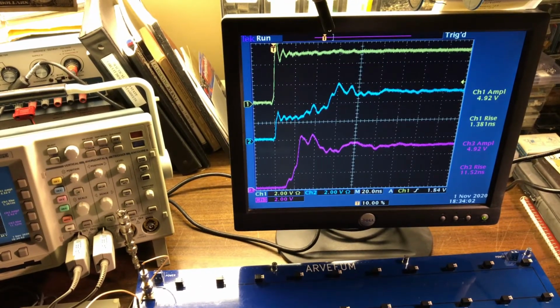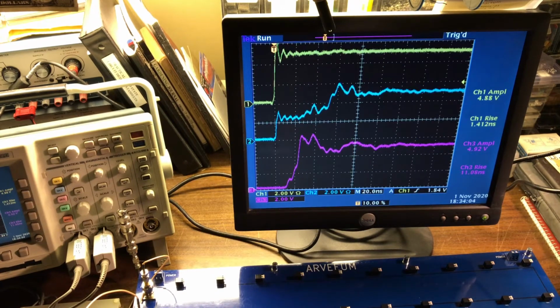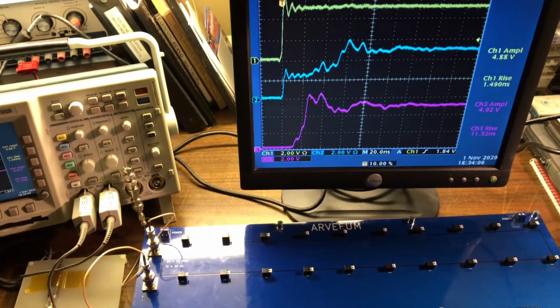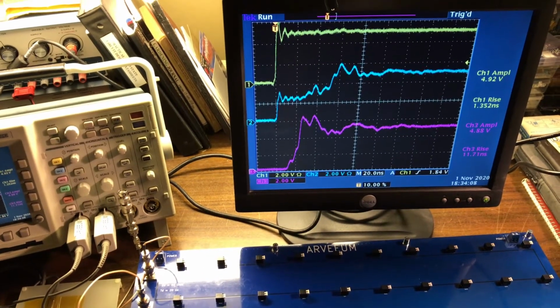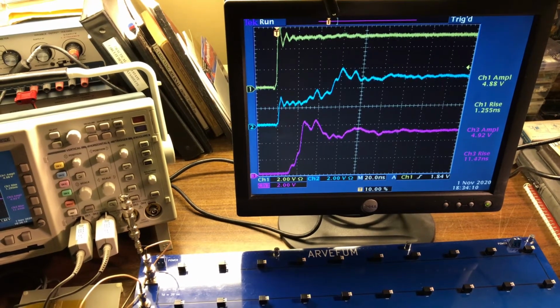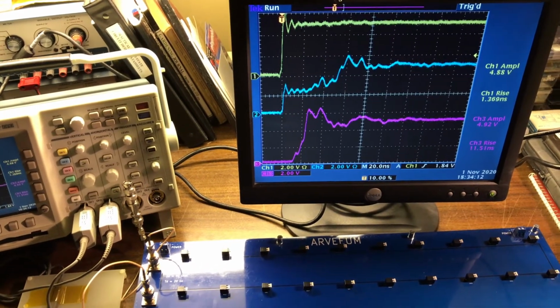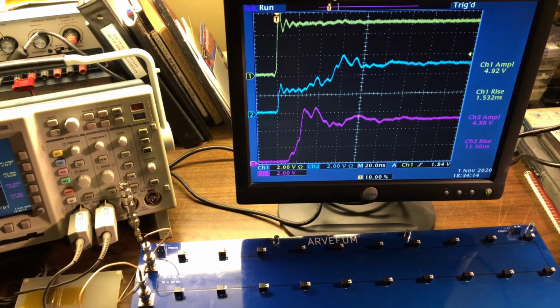What I want to demonstrate here is that you really don't need all these caps. Some people think, and I've seen this when I work on boards, that the capacitors sprinkled on power planes that are being used as reference, as bypass caps for components, are enough to provide a return path for current going in high-speed lines, and that is not so.